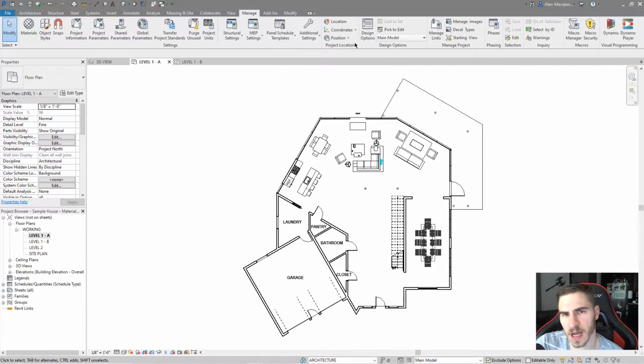I want to show you something that I like to do a lot if I'm trying to show maybe a blank option with nothing in it, or if I want to use design options to hide an element. I would probably only hide elements within design options if, one, I know enough about design options, but two, only for this one specific purpose. There are certain elements within Revit that are profile based that do not translate their materials to a finish schedule.